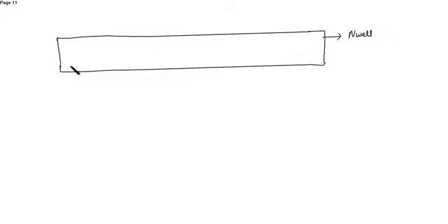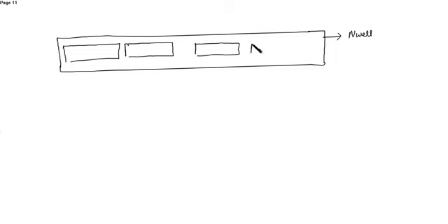Then we have the P diffusion. Now to draw the PMOS. This is P diffusion 1. This is the P diffusion 2. This is the P diffusion 3 and the P diffusion 4. This is the P diffusion layer, and the P diffusion layer was brown in color. So if you want, you can just coat in brown.